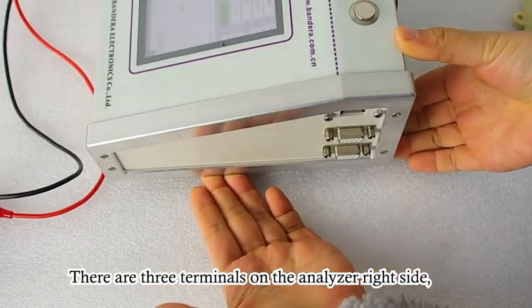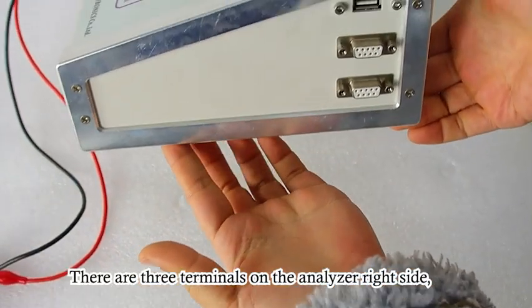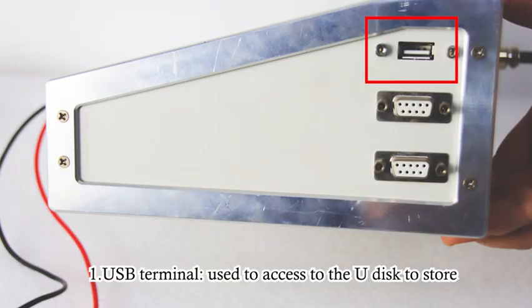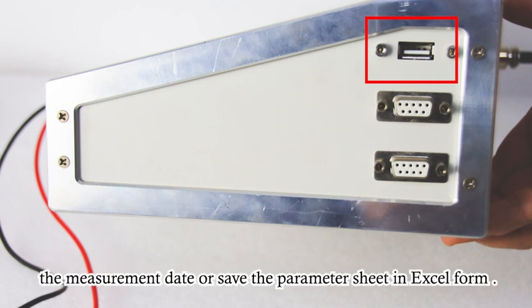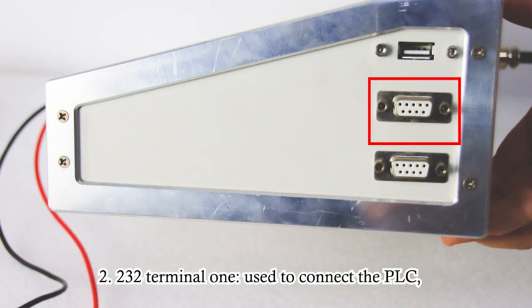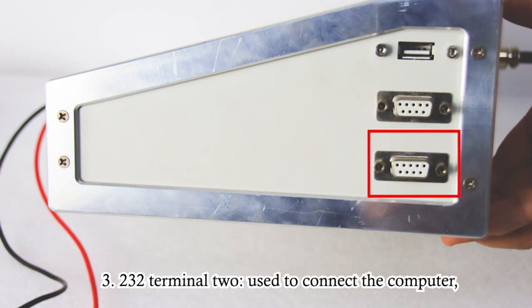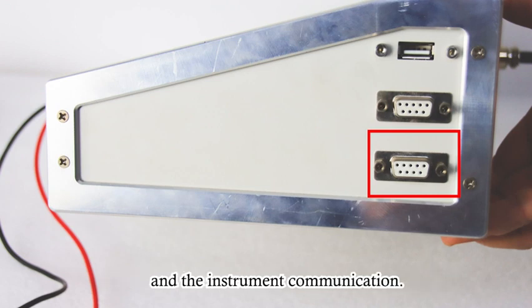There are 3 terminals on the analyzer right side, from top to bottom to display. 1. USB terminal, used to access to the U-disk to store the measurement data or save the parameter sheet in Excel form. 2. 232 terminal 1, used to connect the PLC and the instrument communication. 3. 232 terminal 2, used to connect the computer and the instrument communication.